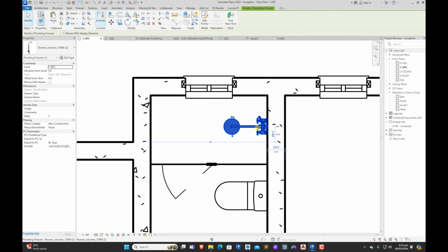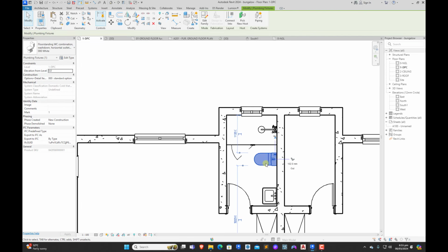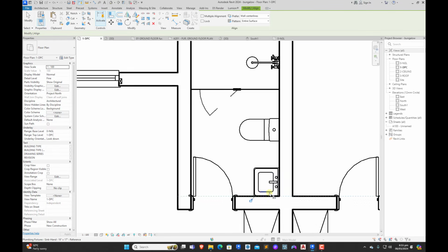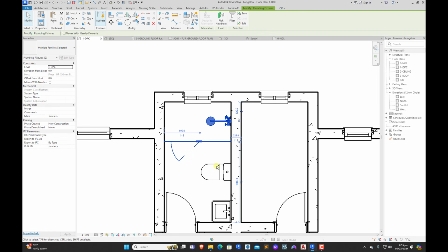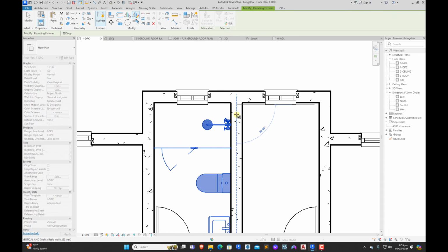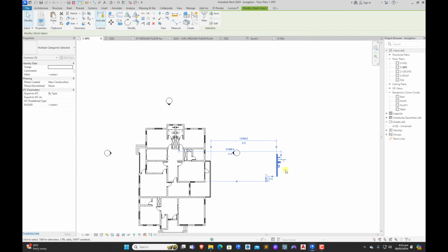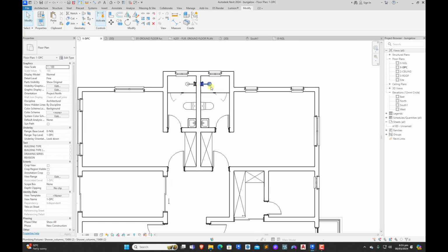Now, this is for our shower. Fine. Now we can shift this WC down a little bit. Then we can align this washhand basin to this wall. Perfect. Now all these things, just click this, select, hold Ctrl to select them, then we flip them to this other point. Perfect. Now this is done. So let's delete this. Okay, now this is it.